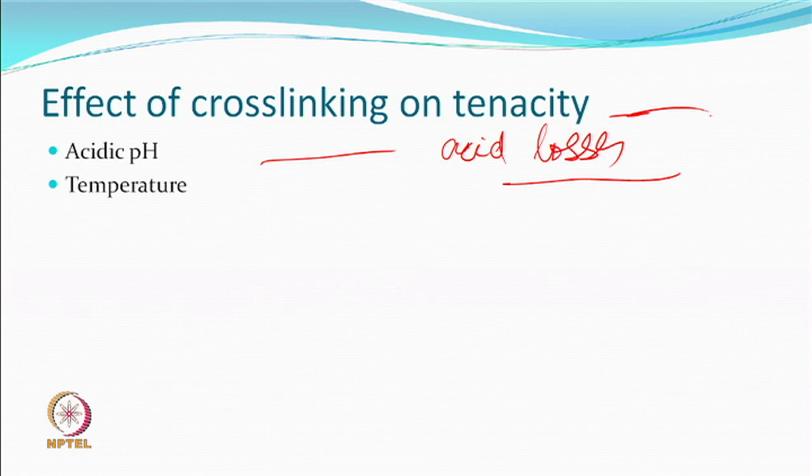You see, what happens is, when you dry, whatever concentration of acid that you have taken in the beginning on the fabric, as the water goes out, the concentration of acid keeps on increasing. So, acids can become concentrated on the substrate and then do damage, but it is fine if they become concentrated only at the time when cross-linking is required, when they are participating in the reaction. If it happens before, then it can cause damage.